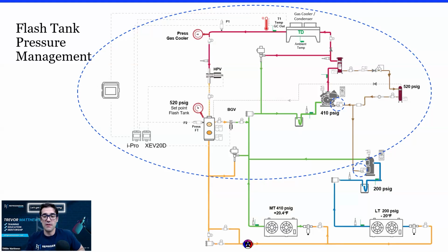So this is something we as technicians may have to limp along with until the next day, until it warms up, and then figure out what caused it. It could be some dirty strainers or something that needs to be cleaned a little bit more. They could be plugging up a bit, and that differential is low, but that just made it worse, right? Having dirty filters or inlet filters, things like that.